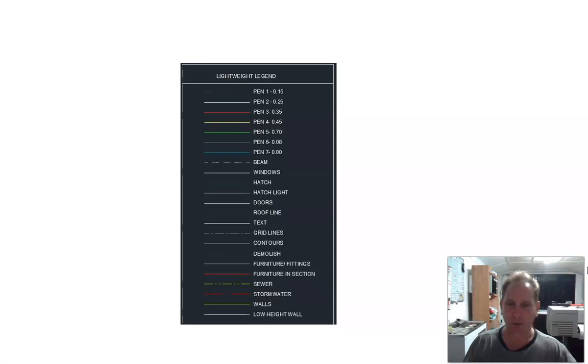Okay, I'll use it for my dog's breakfast or something. Where was I? Slightly bigger letters, like a 0.35 of a millimeter, which is for room names, for example. You use a 0.45 or 0.5, pen 4. That's the thickness of the actual text. When you get to slightly bigger text, like 0.5 millimeter text, then you use a 0.7 millimeter pen, etc.